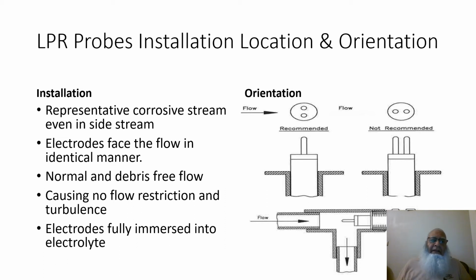The normal debris and the flow regime affect the performance of the LPR probes. The LPR probe causes no flow restriction and no turbulence downstream of the installation. Electrodes should be fully immersed in the electrolyte.